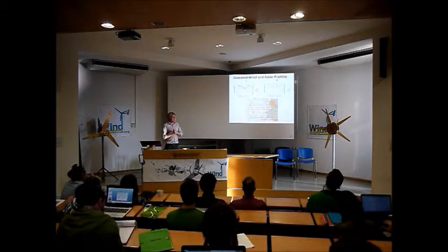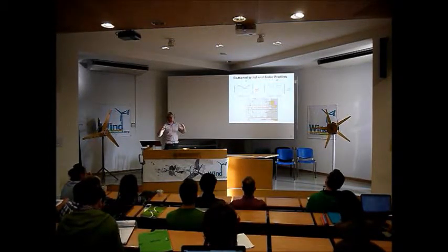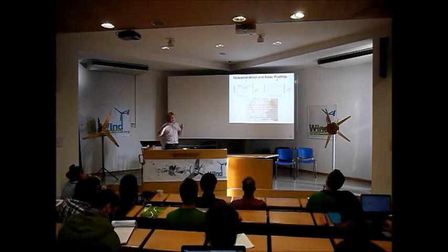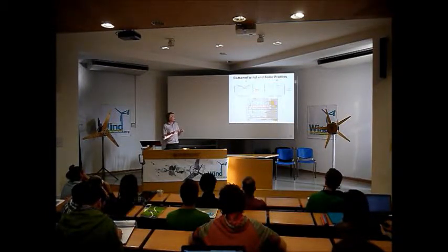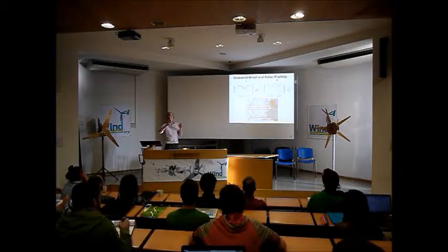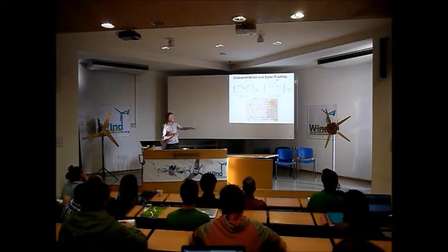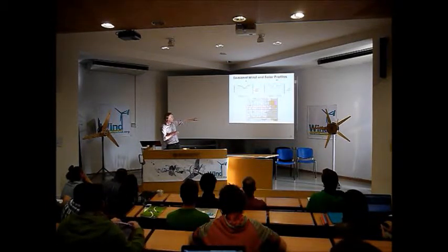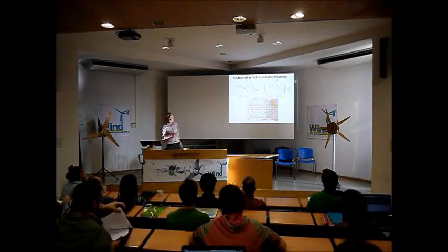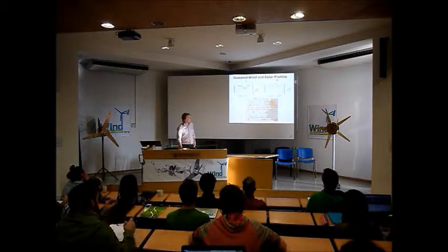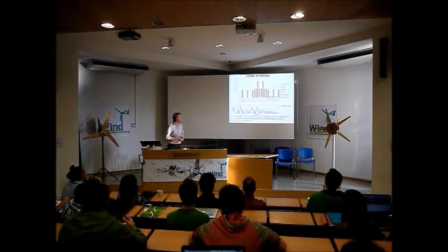It's also important to look at how complementary the wind and the solar resources are. If it's windy at the same time as it's sunny, then wind turbines probably won't be that much use because you might as well use solar power. But if, like in Scotland or in Ethiopia here, there's a season where there's low sun but high wind, that's where wind turbines are optimal. And you can see here in the east of Ethiopia, wind and solar are very complementary, and in the west, they're less complementary. And this data you can feed into Homer to analyse how well it works.